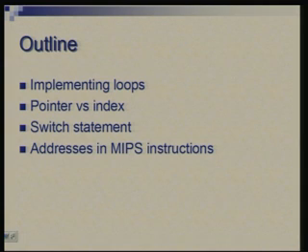Today we will continue further from this point and talk of how we can have further control constructs. We have seen a case of a simple if then or if then else type of structures, where a simple check using typically a BEQ or BNE instruction, possibly in conjunction with SLT, could be used.